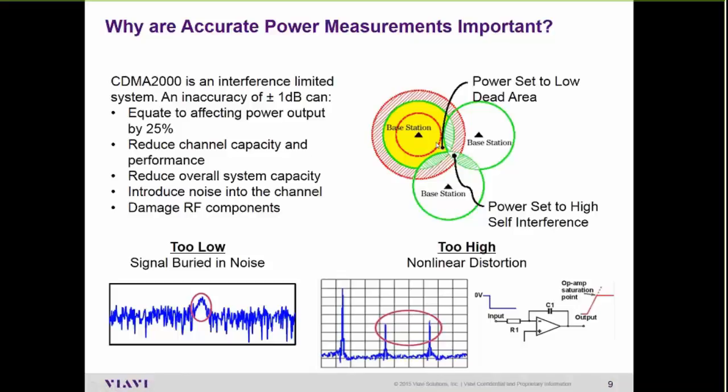And I've seen this in places in California and Washington, various other markets that I've been through over the years. The same goes for if you have power that's set 1 dB too high, basically you get too much signal into a specific area. And with LTE, having too much signal out at the boundary areas can lead to, again, reduced capacity because the schedulers are looking to see what sectors close by are using resource blocks at that particular location.